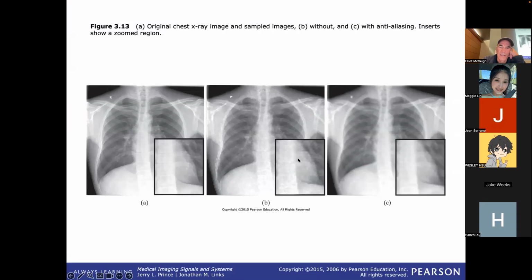And you can see these hashy structures that come out of here because the spatial rate of the digital sampling is aliasing high frequencies that are actually in the image into lower frequencies that come out as these low noisy bobbles. So what you really want to do is filter your data before you sample it to get rid of that artifact, such that you're going to see a blurrier image, but at least your sampling grid is matched to the frequencies that are hitting it.